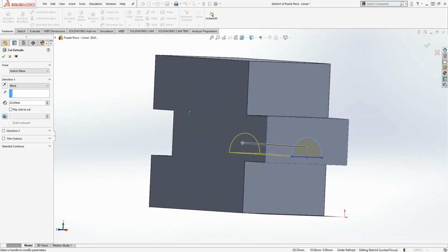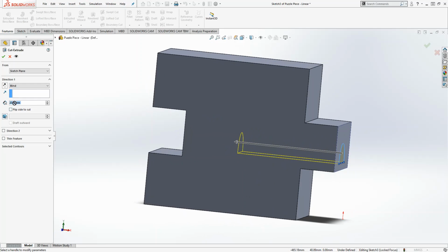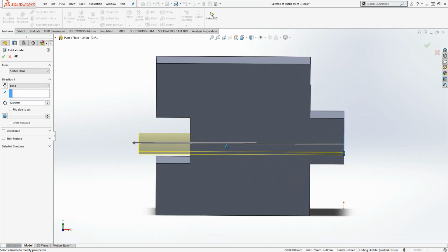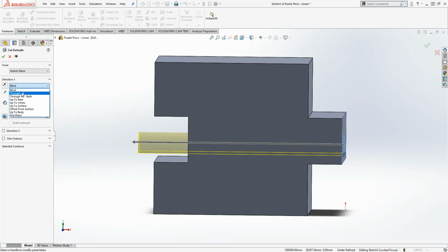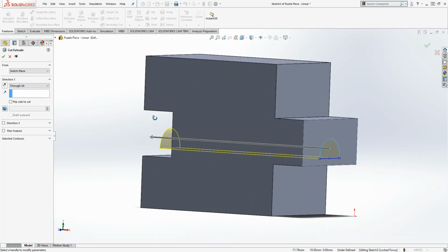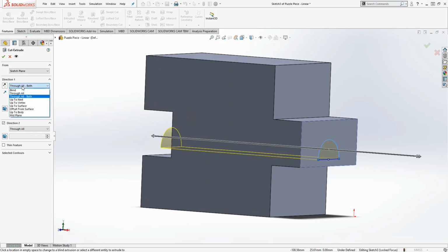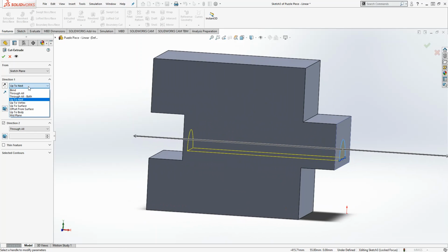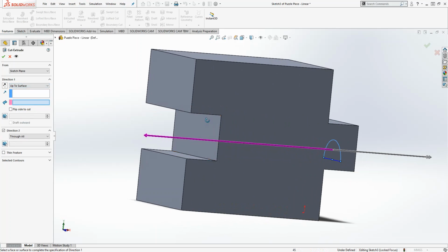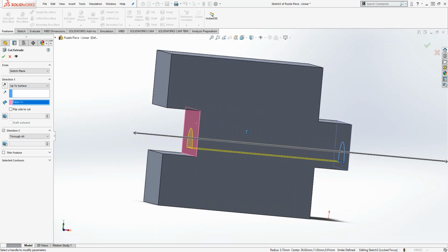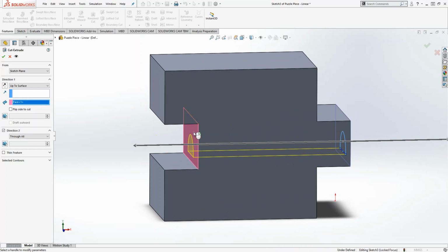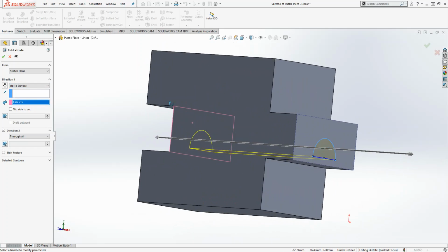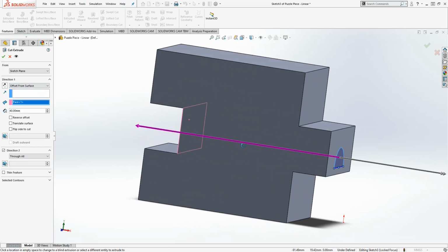So the first thing we're going to do is look at extruded boss base. If I click on extruded boss base, it'll put you at a bit of an angle, and if I move the camera around, you'll see it's already assigned an extrusion of about 40 millimeters. And honestly, it looks good. If we wanted a puzzle piece, we'd probably make it thinner, like perhaps 5 millimeters, and then it actually begins to look more like a puzzle piece.